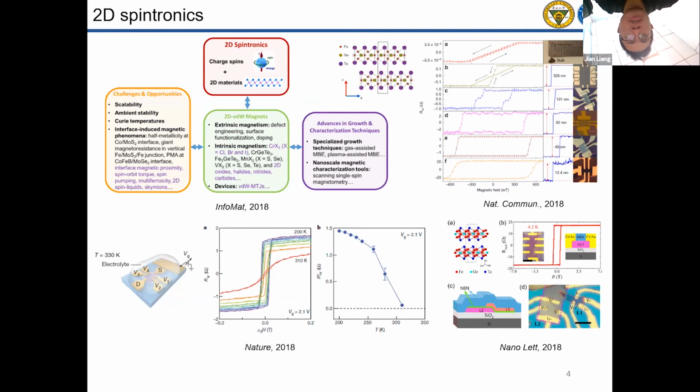A lot of excellent work based on FGT devices has been done, like MTJ or spin wave with hBN and graphene, SOT effects in the heterostructure with Pt. More work is about the basic magnetic research and regulation. However, the research on its magnetoresistance is seldom seen.